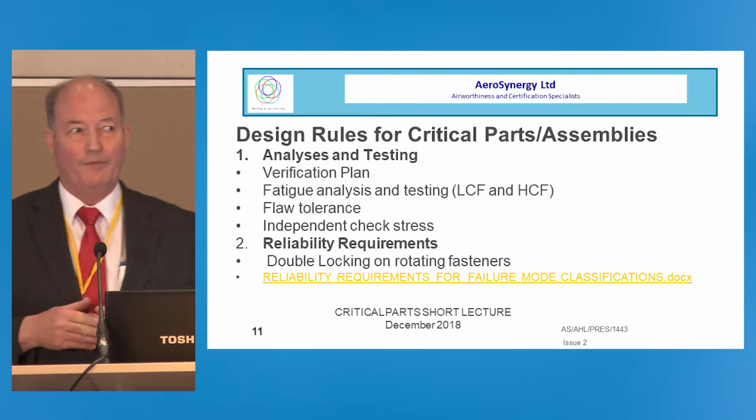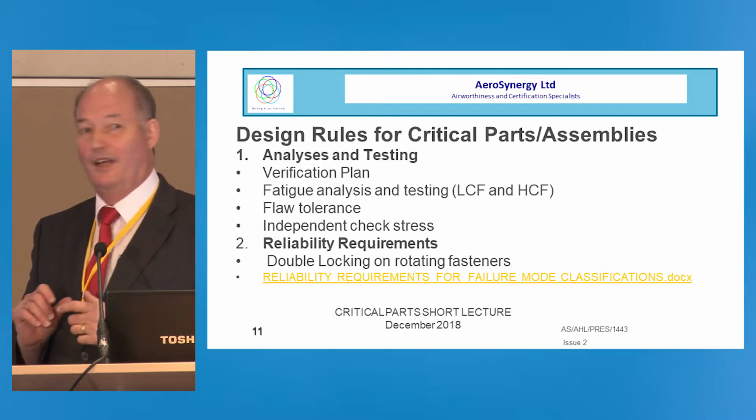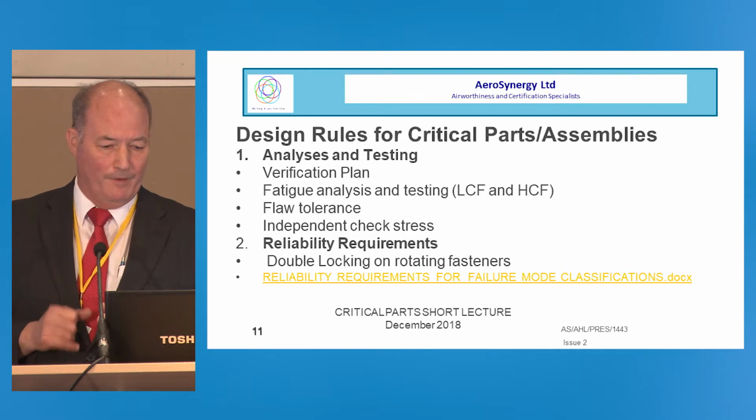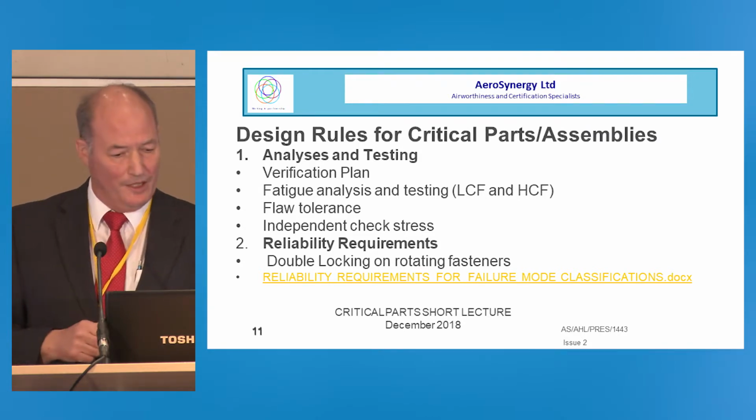Reliability requirements, some things we've already heard about actually, double locking on rotating fasteners. Helicopters are full of those. Anything on the flying controls, etc., has to have a mechanical double locking.